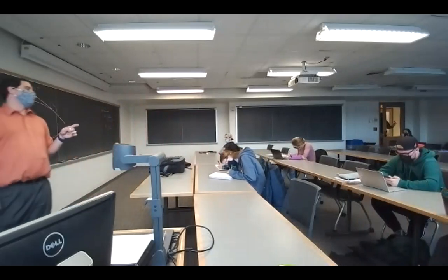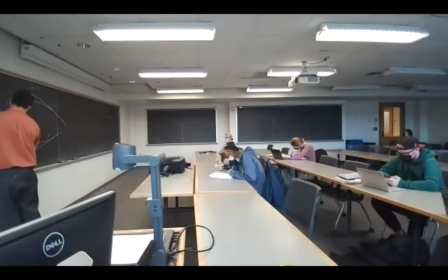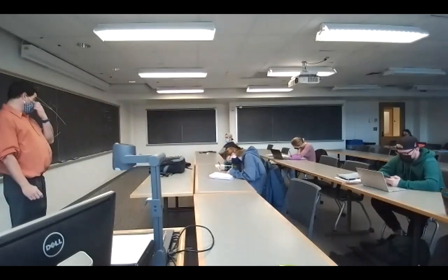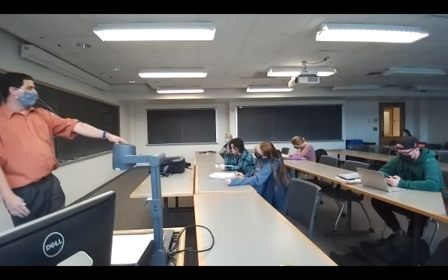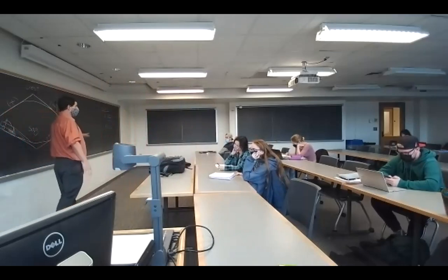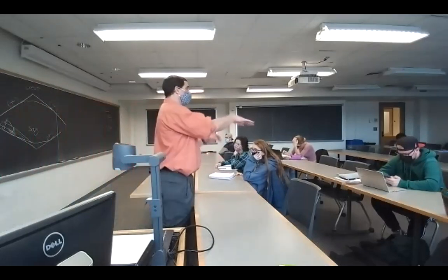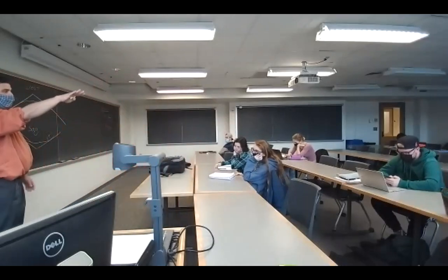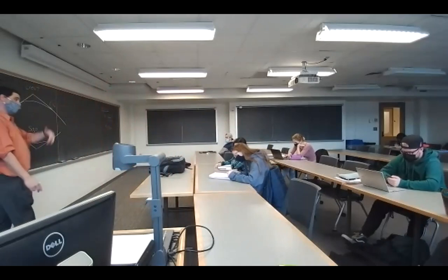The reason I asked Chris about being at night is if this is my car, I'm going downhill. Which way are my headlights pointing? Headlights are typically aimed slightly down. So if I'm going in a sag vertical curve, and it's a pretty abrupt condition, I'm looking more at the roadway and not further out. Right? This is actually called headlight sight distance. And it's typically only for a sag vertical curve.